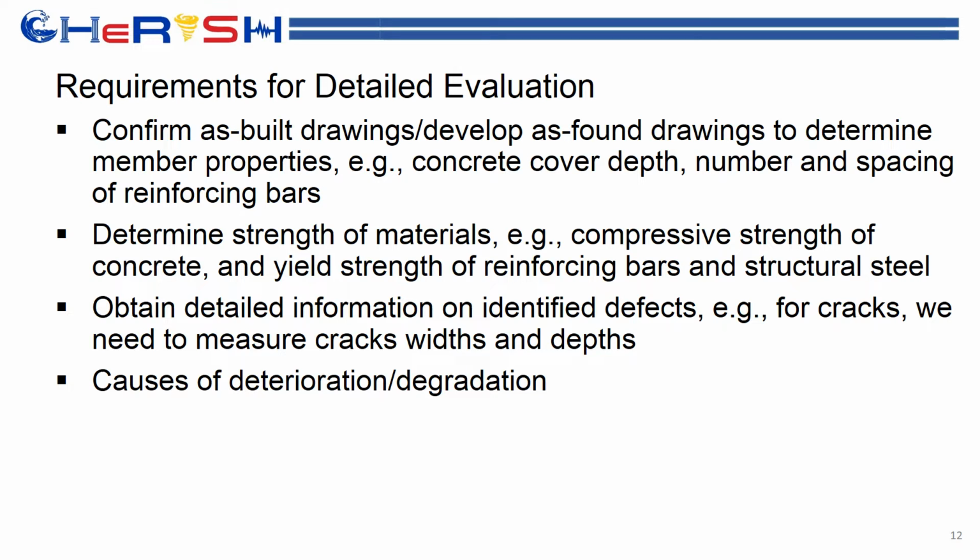Now, after developing what we call the as-found drawing, the next step is to determine the strength of the materials. For concrete, of course, we need to determine the compressive strength, the yield strength of reinforcing bars, as well as structural steel. Now, we can stop there and utilize the information we obtain from these developed drawings as well as the determined strength of materials. But then again, as I mentioned, if there is some information like observed deterioration, defects, or damage